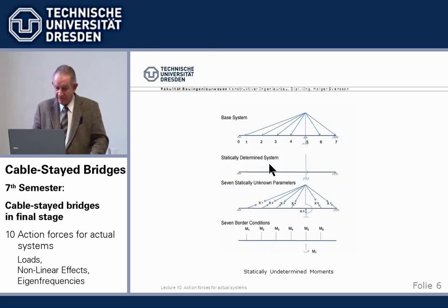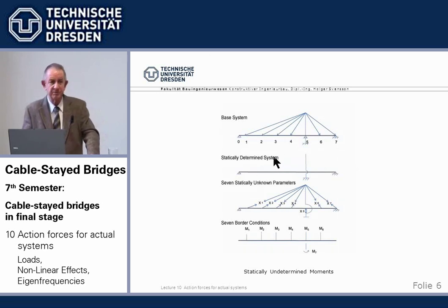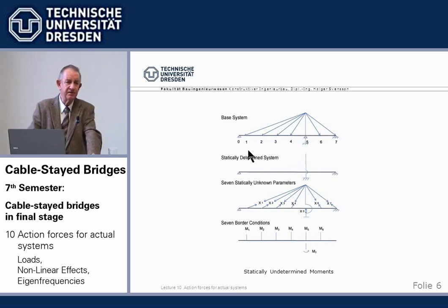Well, a little bit back, you know all that, but just the statical theory behind it. We have here a base system, which is statically indeterminate. By first approximation, the cables are the statically indeterminates.